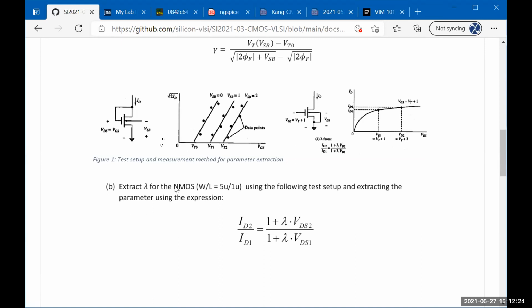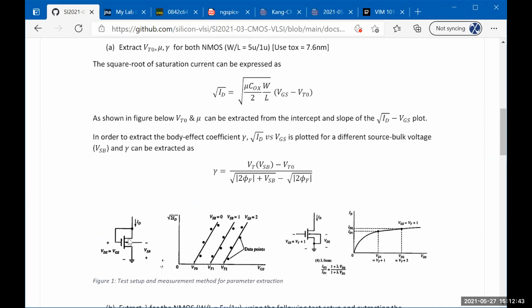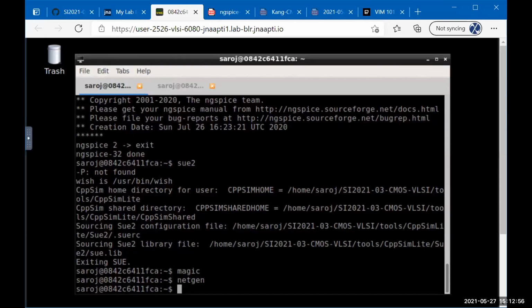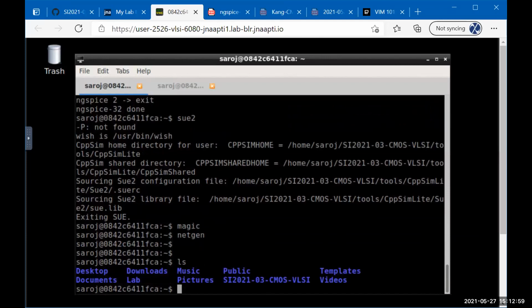So we are trying to give you that whole process, and also give you an insight into those models, like what is happening inside the model. Obviously we don't have access to the fab and probe station and all that, but we have access to a very good model. The model we are going to use, the 0.5 micron technology, the scaling, is a level 49 BSIM 3v1 model. That model is read only now, but you can copy it to your directory if you want to take a look at it.